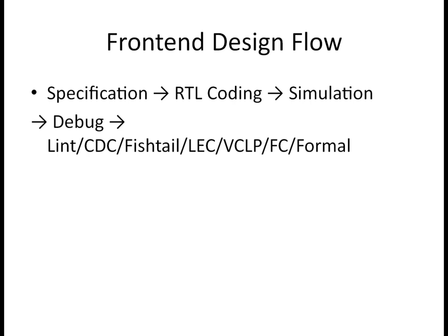There will be many modules in the integration, right? In the top level RTL, we check whether the top module is connected to the other modules correctly or not. We can check as per the depth we give. This tool can go from top level to sub block 1, sub block 2, and so on. We can check the connectivity of clock, reset, whatever we mention in the TCL file. It can do the connection checking.